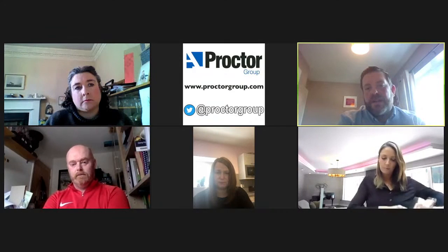So yes, I would agree that the methods in BRE 211 are less stringent, and I think it's something the industry has recognised. Watch this space, because it will be revised and likely to be in line with the standard for CO2 and methane protection in the near future.